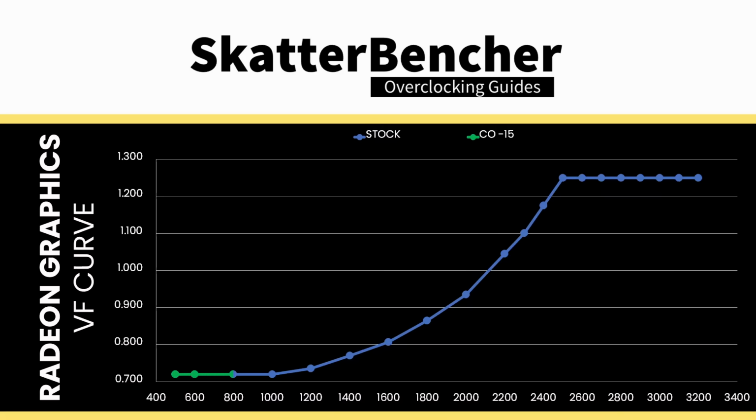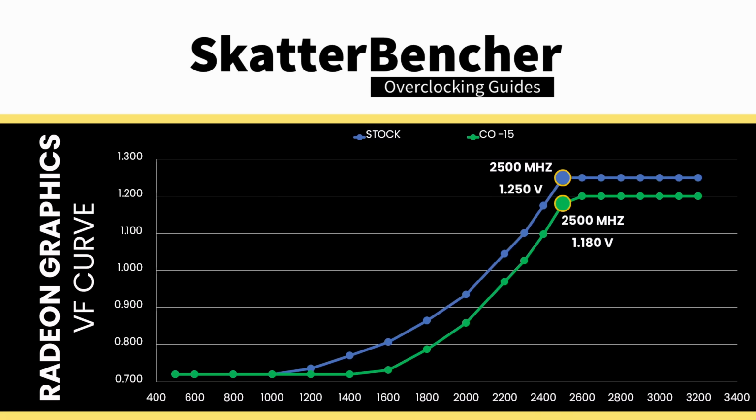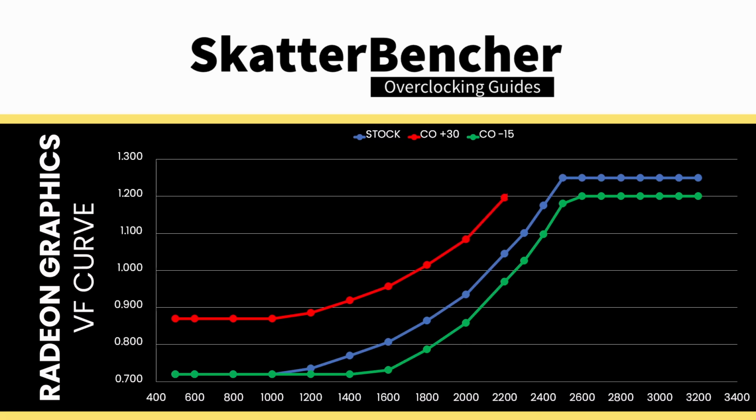If we set a negative curve optimizer, we can shift the entire voltage frequency curve along the voltage axis, and suddenly we need a lot less voltage for every operating frequency. For example, at default for 2.5 GHz we needed 1.25 volt, but with a minus 15 curve optimizer we only need 1.18 volt. Similarly, a positive curve optimizer will make us use more voltage for every operating frequency.